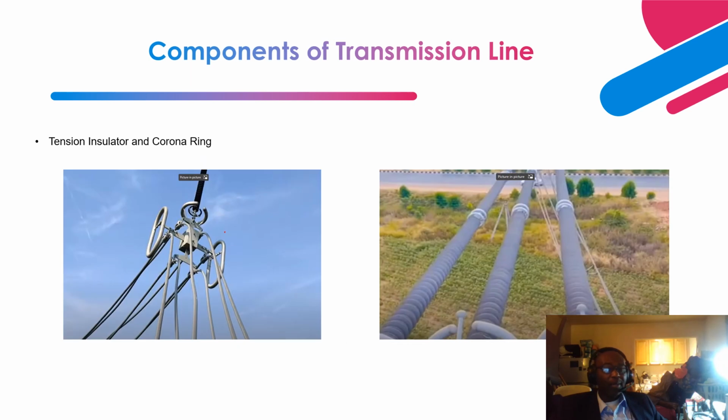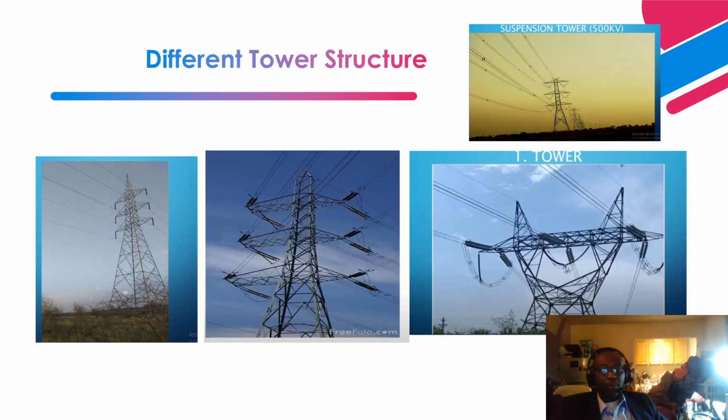Okay, so this is a deeper look into the corona ring. I explained what the corona ring is. Its goal is to provide grading voltage to reduce the electric field stress that can be experienced at this connection point, and to prevent breakdown of the insulator. So if this insulator is a polymer or porcelain, and now you have a live connection point here, there will be high electric field, and the goal is to put this corona ring over here so that you can have V over D, and your D will be greater, and your electric field will be much lower.